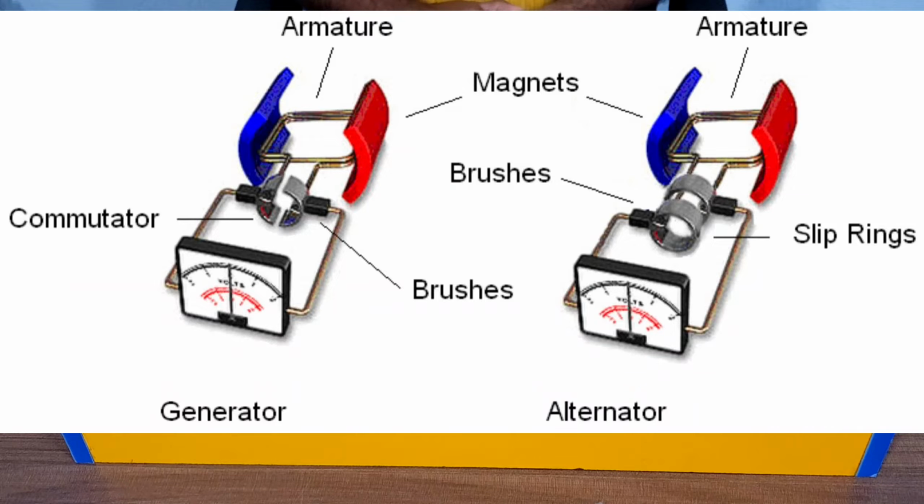And as I mentioned, for distribution and transmission, AC is easy to distribute using transformers. You must have seen the transformers in a substation or outside your society. They are step down transformers, because when electricity is generated at the power plant, voltage is very high, some lakhs of volt, and when that electricity reaches your house, it is 230 volt. So we use two types of transformers, step up transformer and step down transformer. And DC is difficult to distribute as transformers cannot be used.